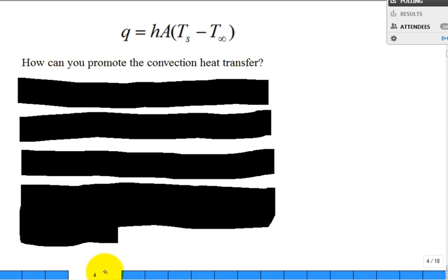What is the purpose of adding that little fin in our radiator? It's to make a larger rate of heat transfer. In this basic equation, we would like to have a large Q. Mathematically, that's how we interpret it. And Q is a product of three things: h, A, and delta T. This is the type of thing I hope you don't leave this class without. But I'll be honest, when I took heat transfer, I definitely left this class not knowing this type of basic stuff. Oh, I could talk about all kinds of mathematical gyrations to solve problems on exams, but I lacked some practical knowledge of how the class applied.